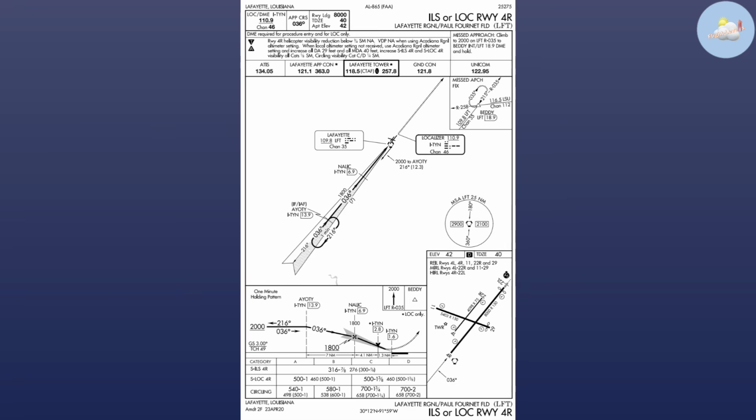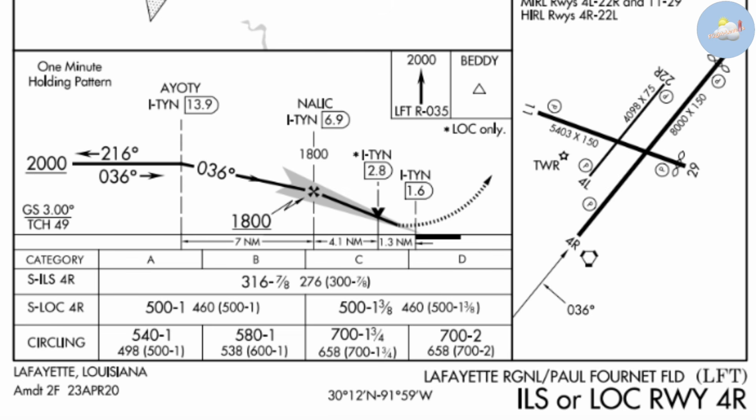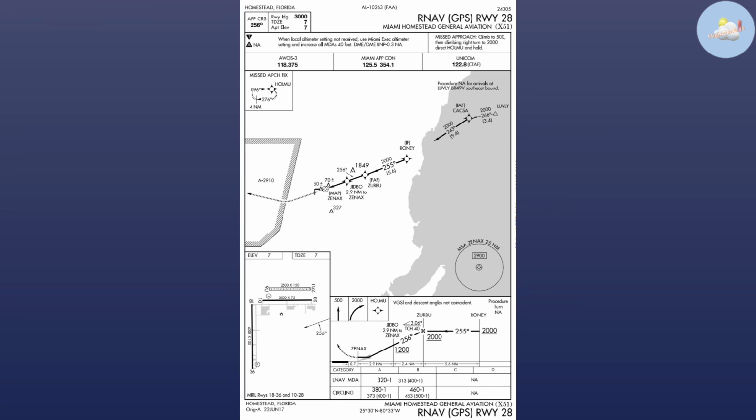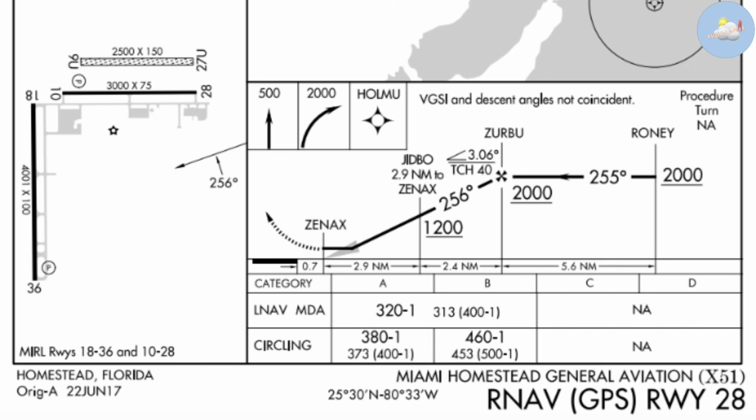First off, we have different kinds of instrument approach procedures. The gold standard and the best thing that we have currently are precision approaches, which include glide slopes. Whether this is an LPV or an ILS, this gets you all the way down to decision altitude and provides you guaranteed obstacle clearance all the way down to that decision altitude. In the absence of a precision approach, we have non-precision approaches, and these give you step-down fixes with altitudes as well as a minimum descent altitude.